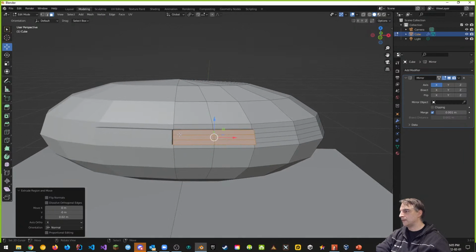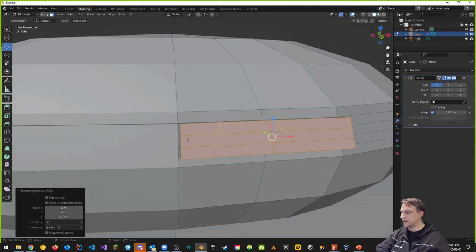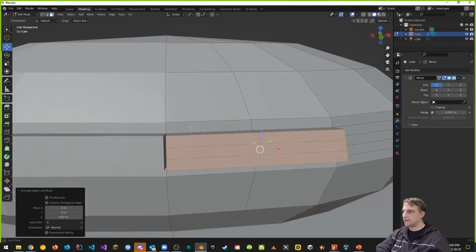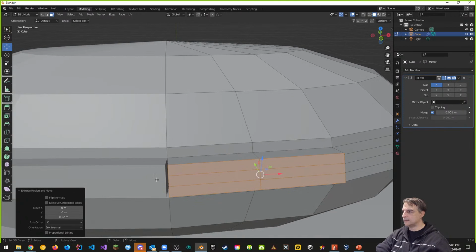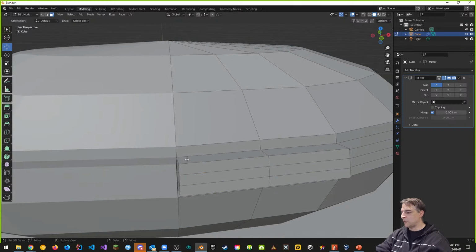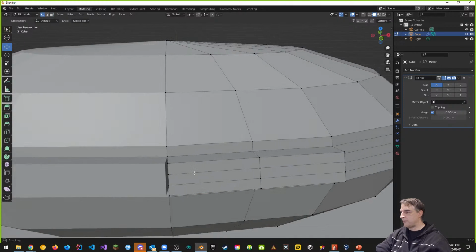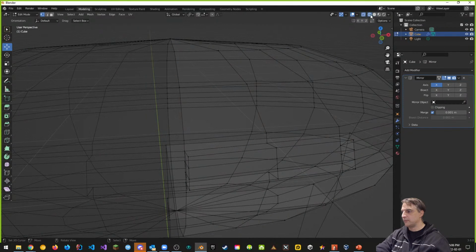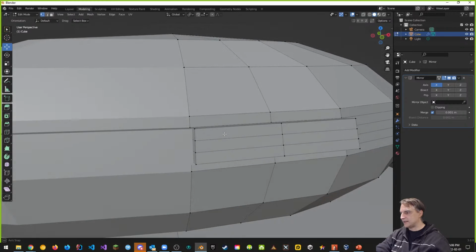0.02 meters, right? There is a bit of a problem here, right, at the side, because not only did it extrude all of these, but it also took away our connection in the middle. We could certainly leave it this way, but I think it's best we put these together, and there's a way of doing that. So let's deselect those and go back into vertex select mode, but not before we select these ones. I'm in solid mode, and this is wireframe, and that's solid mode up here. I want to stay in solid mode, and I want to select these 4 vertices. So select, select, select, select.